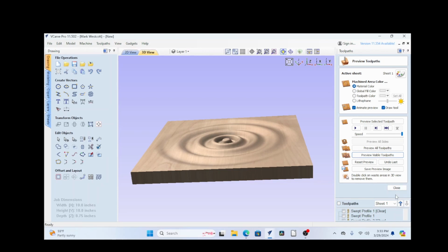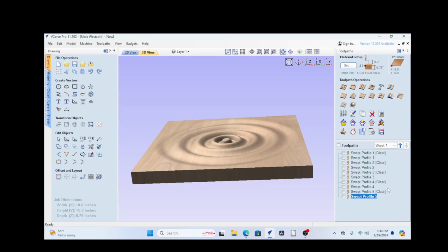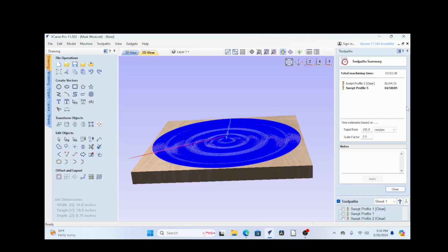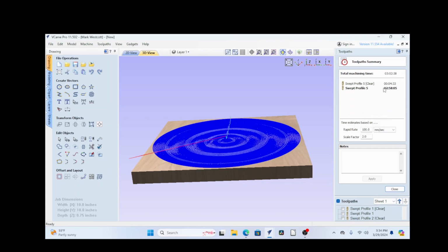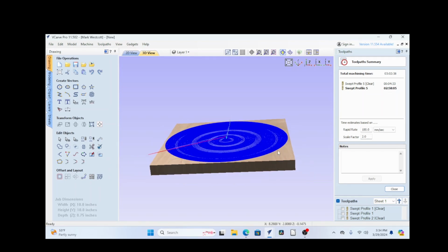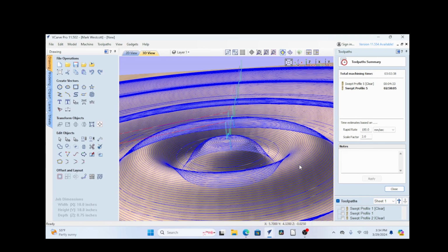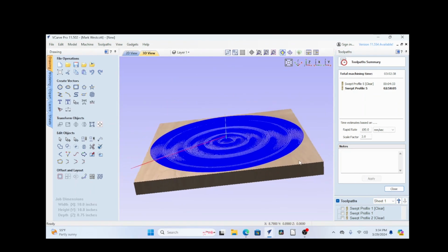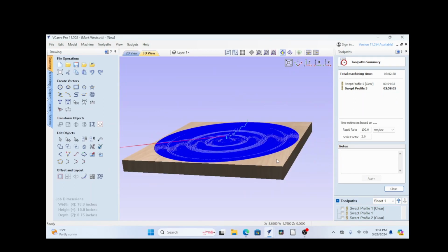And just so that you get a feel for how long these tool paths take, because they can take a while. Let's just take a look and see what these two tool paths would have taken for time. So the clearance tool path, not too long, about 4 minutes, but the sweep tool path, when you get a big path where you're only doing 8% turnover, it's doing an awful lot of passes in there if you go in. And at the rate we were going, it would take a long time to cut something this large out. But it will do a nice result.